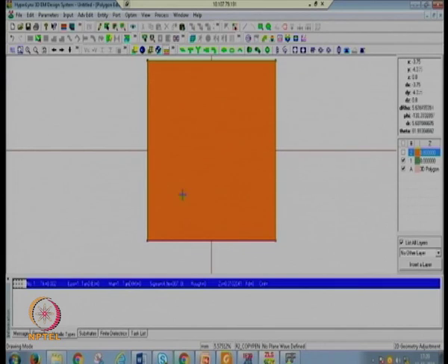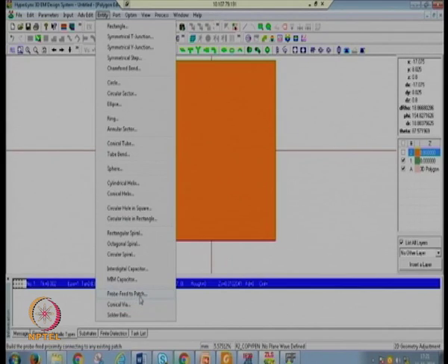Now so far you have designed the rectangular MSA, and the next thing is you need to excite it. So to excite it, we need to define a port. So the length in this case is around 16.74. So here we are not using any broadband technique. So the approximate feed point location should be from L by 6 to L by 4, just to give a start point. So let us take it around 2.5. Select entity, go to probe feed to patch.